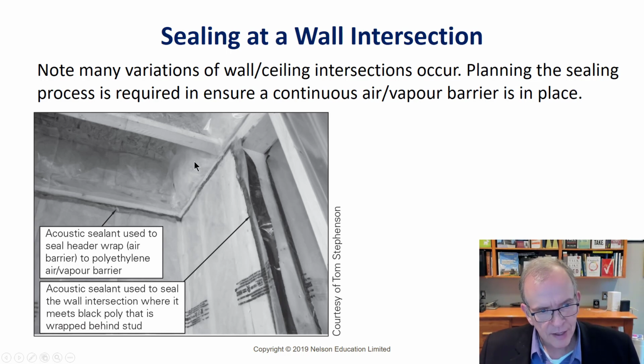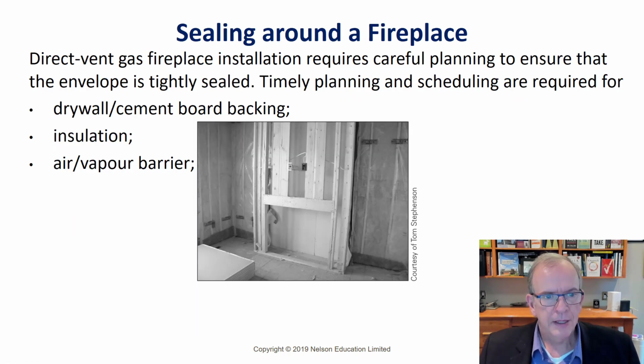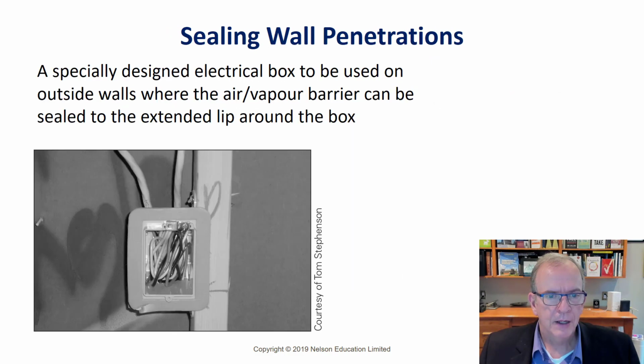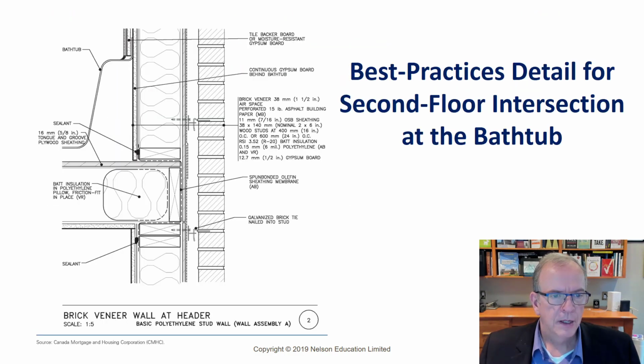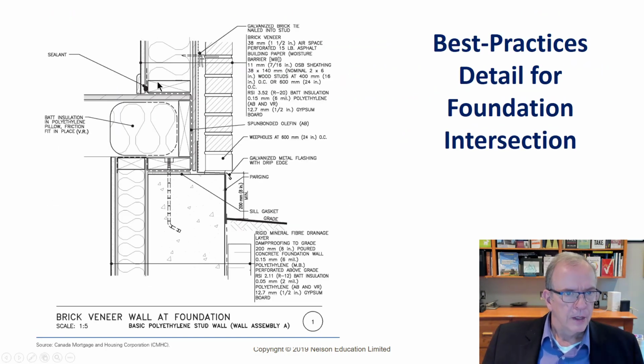So in these sections, this is acting as a vapor barrier, right? It's not acting as an air barrier. But they usually will have, if I go back a few slides, in this section here, this is acting as an air barrier, right? In this part, the poly that you saw, they don't draw it that well here, but the poly that's coming up inside, it's acting as a vapor retarder.